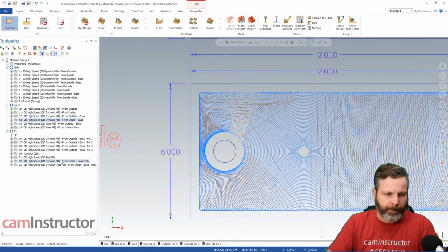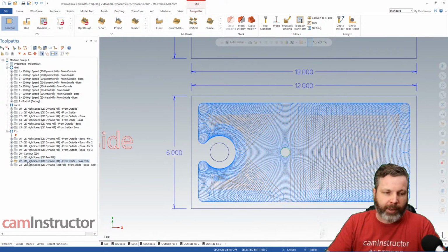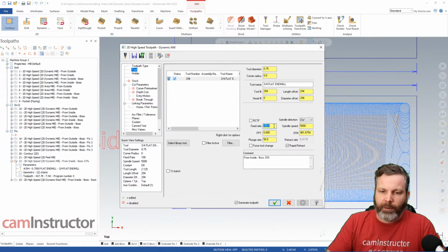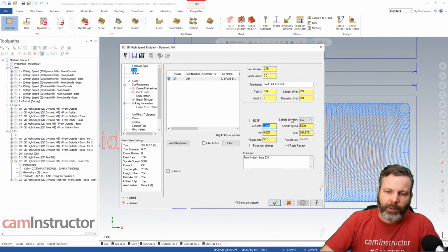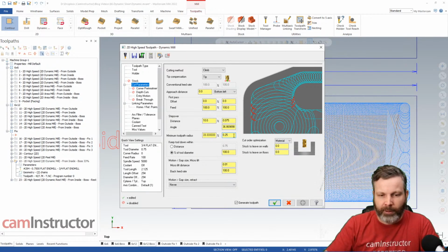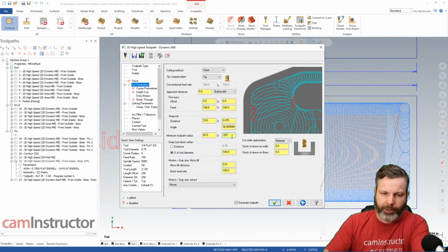So what we're going to do here is just not cut it. Plain and simple, we're just not going to cut those areas of the toolpath with our tool at the higher feed rate. To be even more exact, maybe this is 300, 250, whatever it is. And with this, we're going to limit how small we can get with this toolpath. So I don't want this to cut anything less than a 1/4 inch radius. You want it to be extra safe, call it 400, call it maybe 60%, whatever it is. But I'm going to leave this at 1/4 inch, not 25 thou, sorry, 1/4 inch for now.